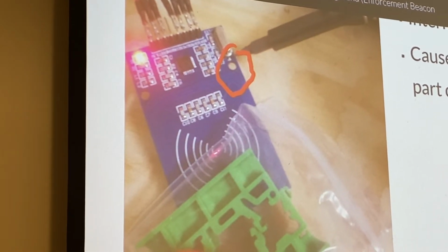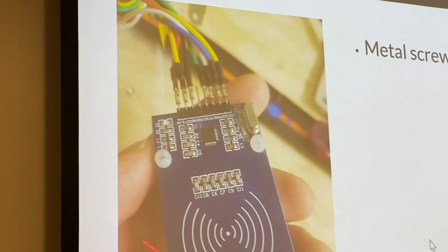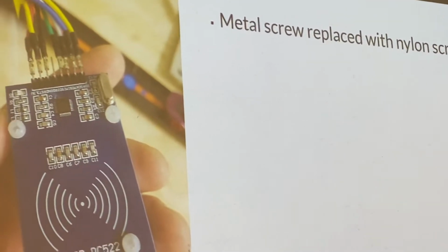So easy fix, we just replaced those screws with nylon screws. So no metal to metal contact whatsoever. And that basically solved our issue.